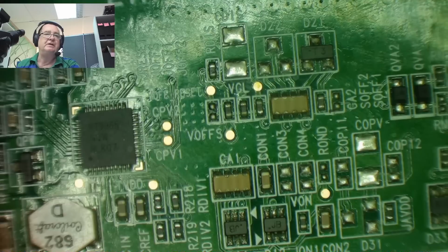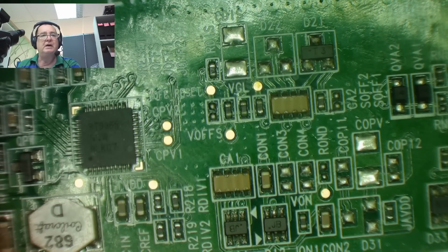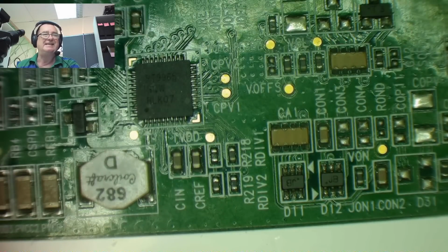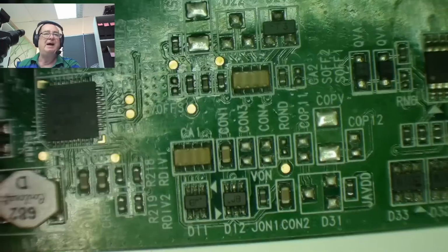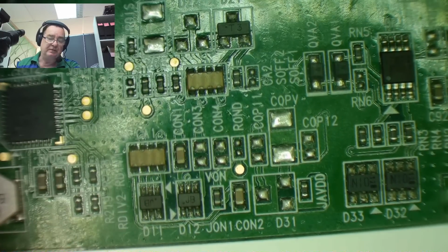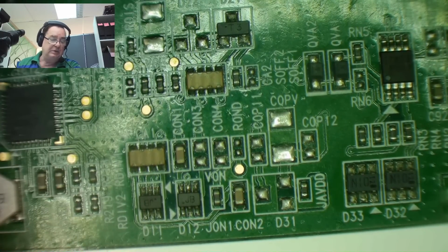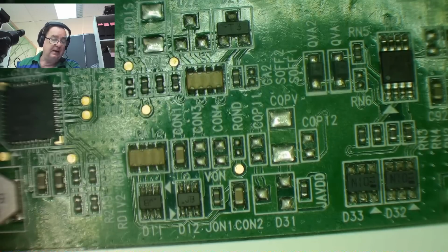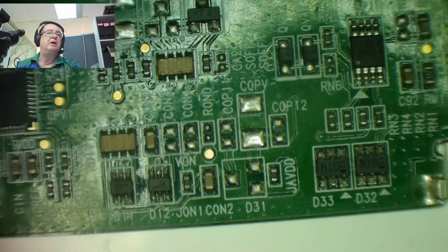And I said there's nothing on here that's 16 volts. But because the AVDD is 8, and that was suggesting 10, it may be less than that. It might be somewhere in the region of 10 or so. I'm guessing. We don't know what the voltage is going to be. But I can't see any test points that are marked as that.